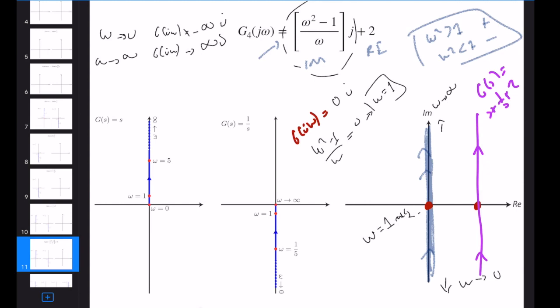Okay, there will be a real part. It will be a line intersecting the positive real axis. This is technically the P action. And here this is the I action. This is the D action. And as you can see, integrator and differentiator are affecting different frequencies because of their low pass and high pass structure.